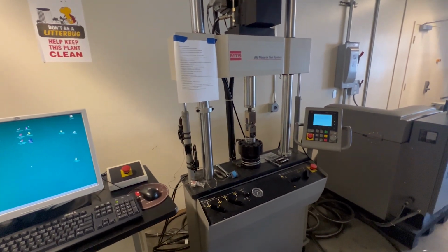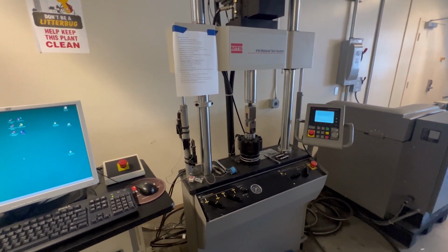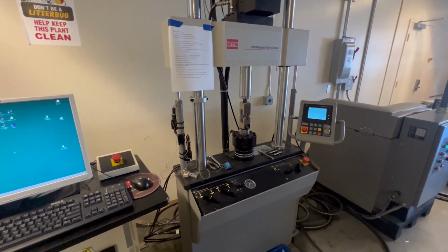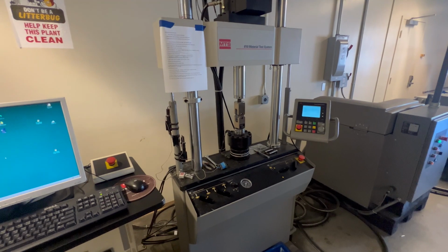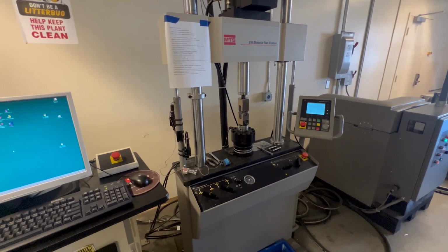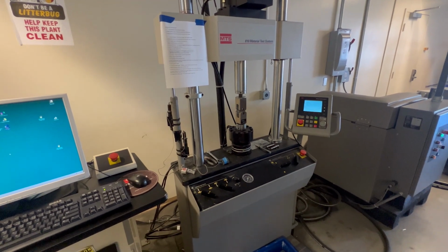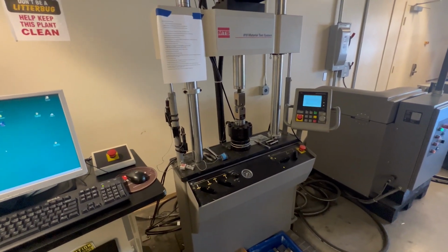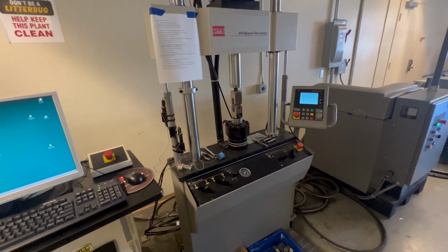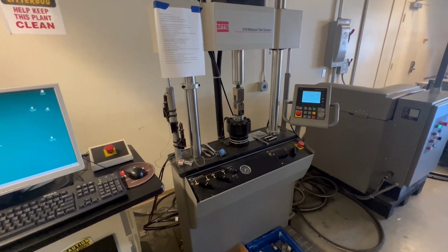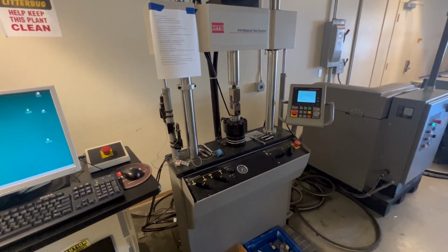Alright, after they find the sample and the testing procedure, I'm going to install the sample or specimen onto the fixture and then continue to execute the pre-cracking and then the K1C constant load increasing test until the specimen is fractured. I will stop the video here and come back after the installation.